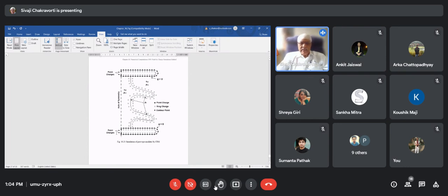So even if you rotate around the axis, it remains a point. It's no longer a ring. So we put 2 point charges at the axis of symmetry. The rest are ring charges. And then you have the insulator contour. Since it is rotationally symmetric, I can use ring charges, because if you cut this geometry by a plane perpendicular to the screen, you will always get a ring of various diameters. So we have put all these crosses, they are the ring charges. In this way, we simulate the systems in the charge simulation method.